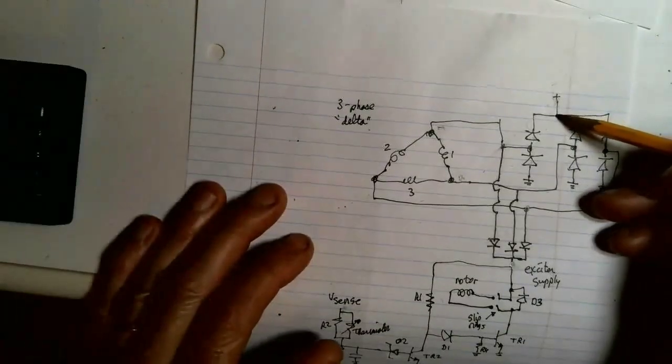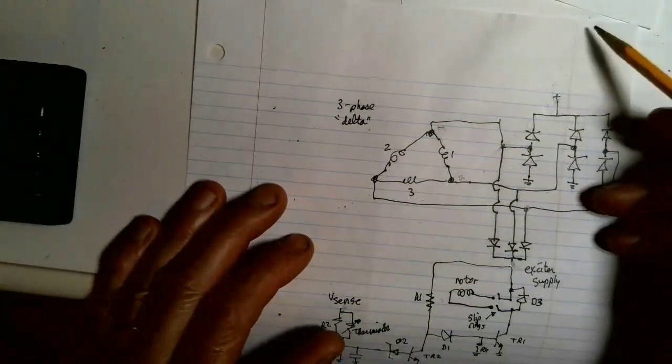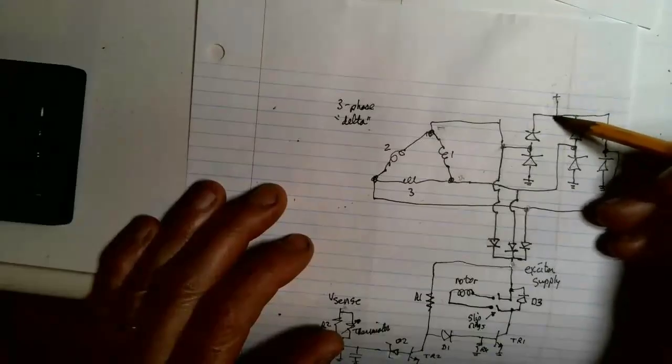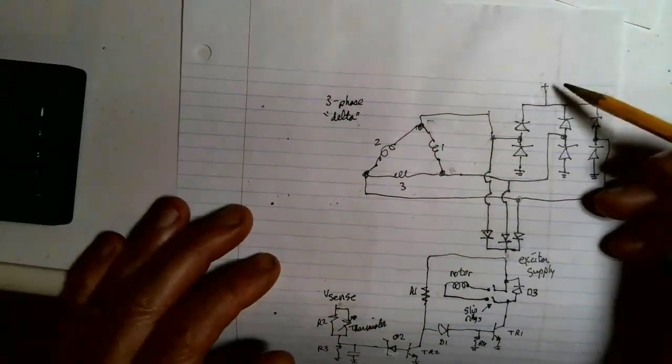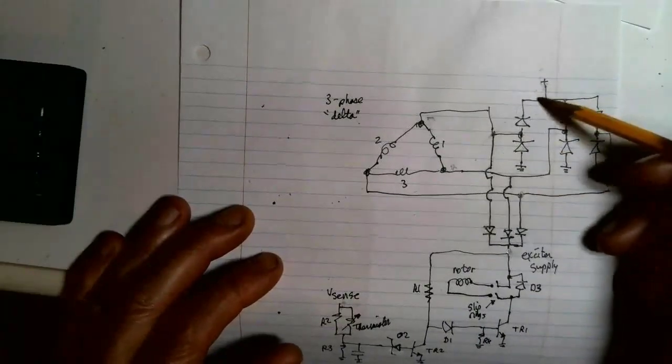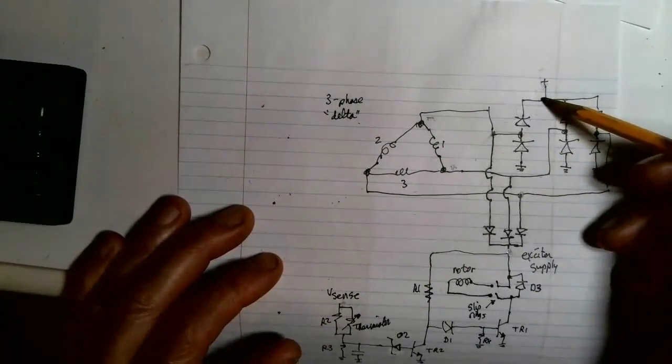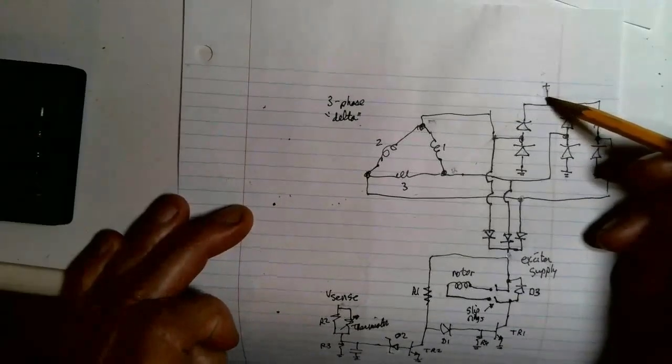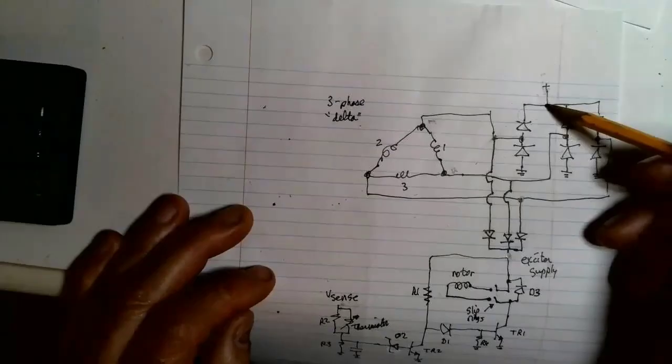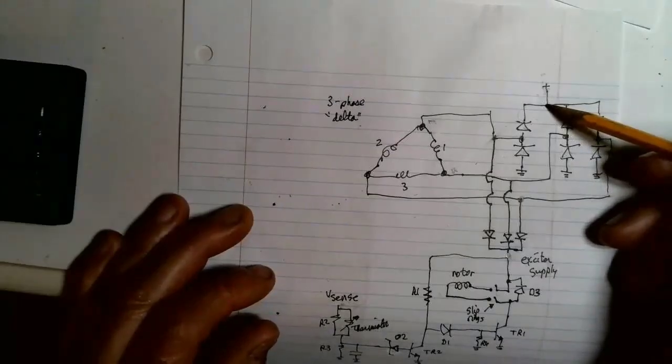And the reason why this remote sense is a strong plus is this is a 100+ amp alternator right here, and so you could have a fair amount of drop in this connection, and you might lose half a volt before you ever get over to the battery, for instance, just in the wire that runs from this node over to the battery. So this remote sense allows you not to have to worry about that. You can regulate the battery voltage, and if this voltage needs to be a little bit higher than the battery voltage to make that happen because of the drop in the wire, that's okay. So that's why they do remote sense.